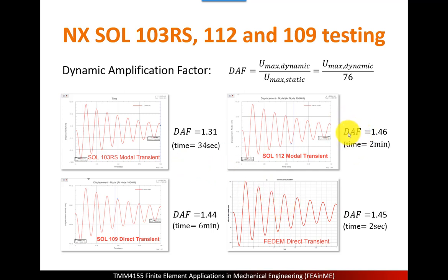This solver is calculating the mode shapes before it's actually calculating the modal participation factors. Both these two solvers will calculate 4 independent equations representing the 4 modes, and then calculate the amplitudes of the mode shapes for each time step, and then multiply these 4 amplitudes for each time step with the mode shape or eigenvector.